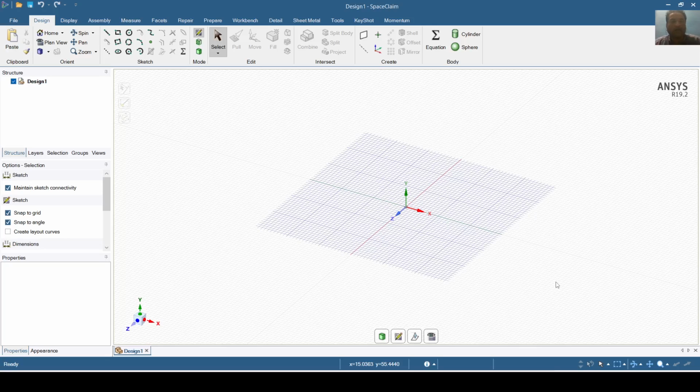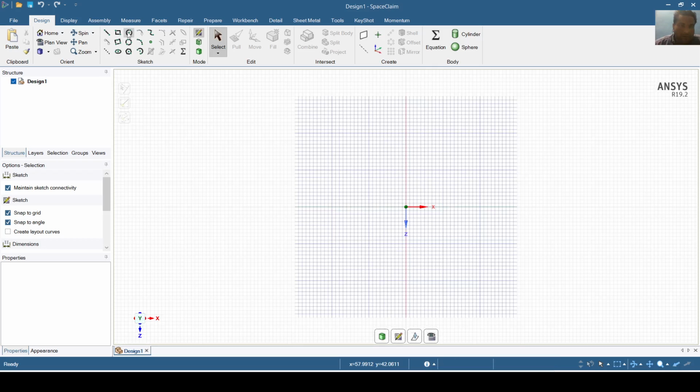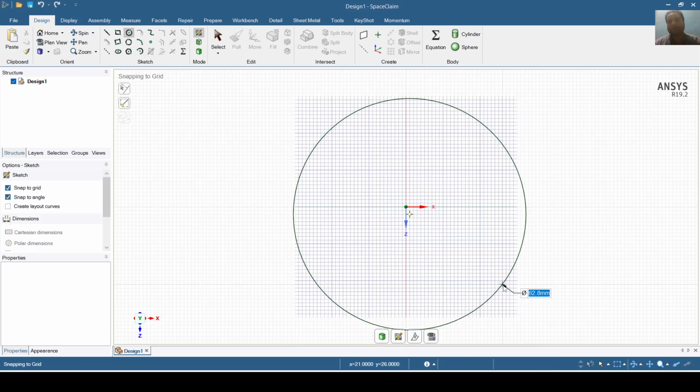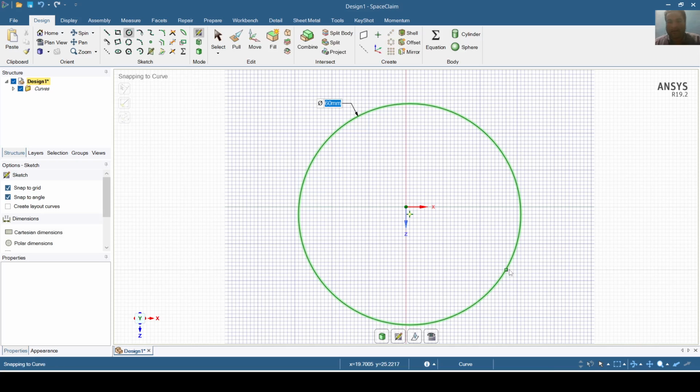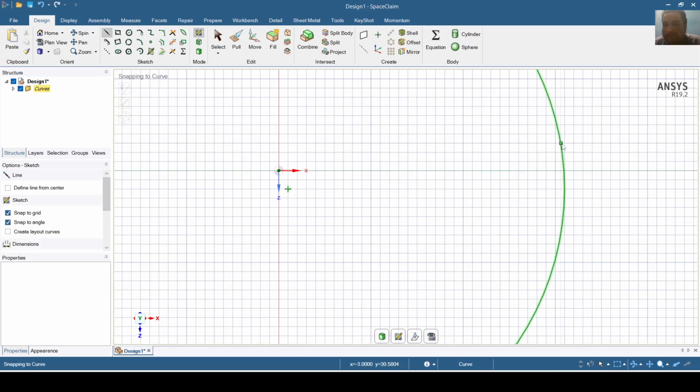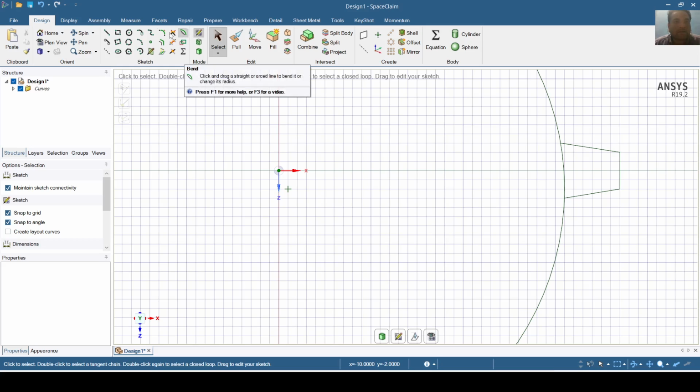Now we will learn about how to prepare a gear. For this purpose, first of all I will go to plan view, and I will create a circle here of diameter say 60 mm, and now I will go to this line tab, and I will create a profile for the gear, and I will click this point, and this point, and this point and complete this profile, and I will now create the rounded corners